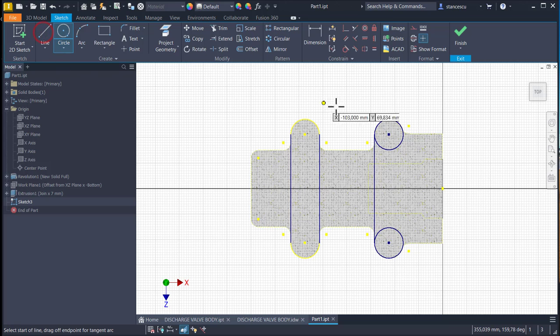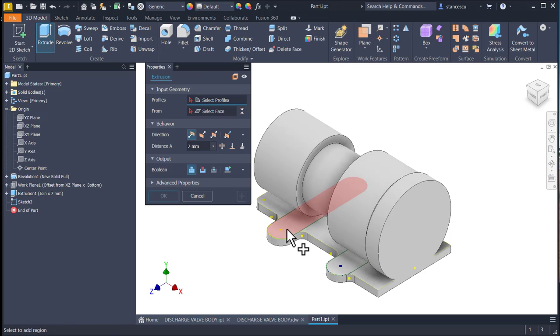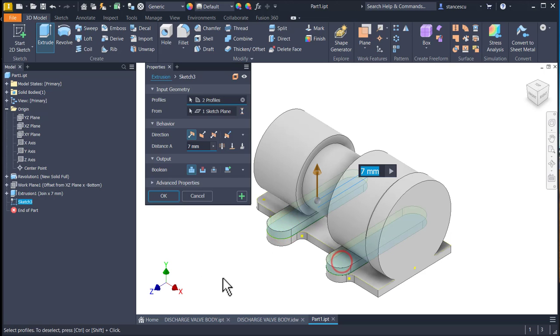We draw a tangent line to both. You know the procedure. Select a random point and draw a tangent, common tangent. I trim these two, and now I have what to extrude. Extrude 1, 2. What dimension? 30.